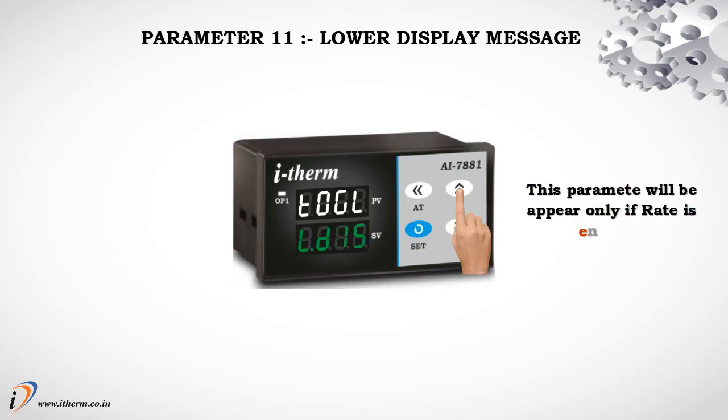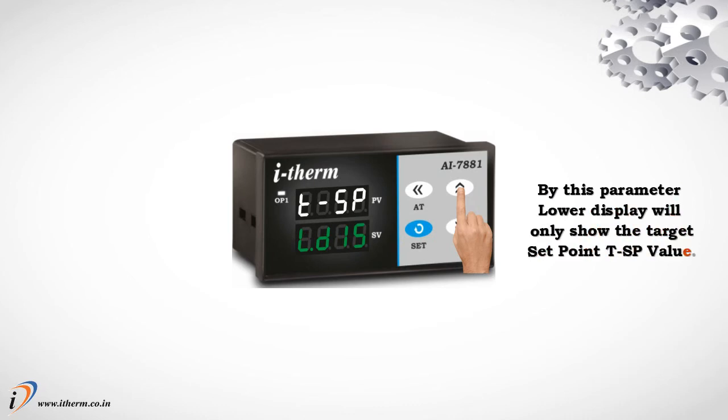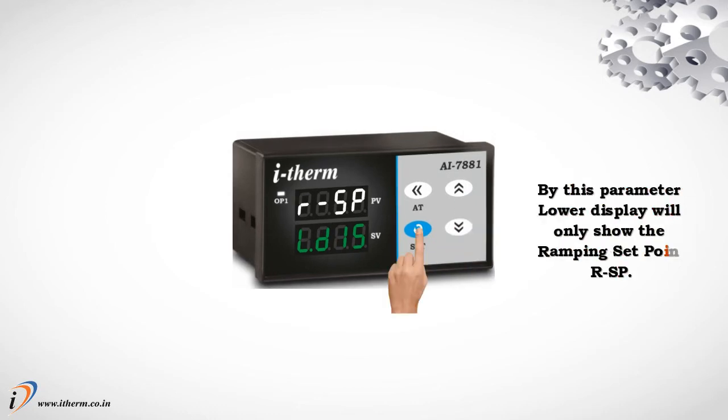Parameter 11, Lower display message. This parameter will appear only if ramp rate is enabled. By this parameter, the lower display will only show the target set point, T set point value. Or the lower display will only show the ramping set point, R set point.